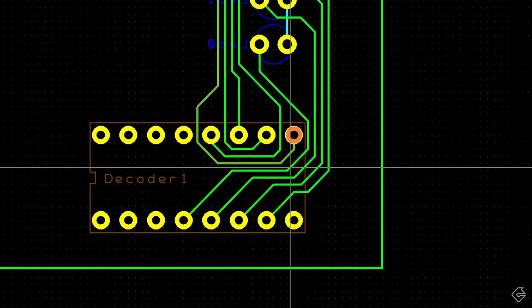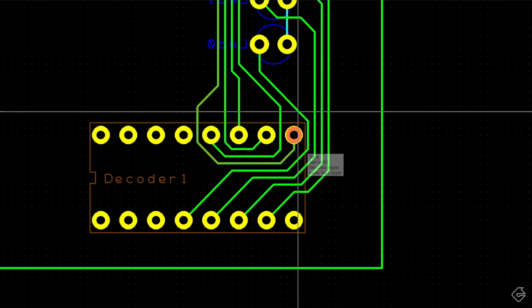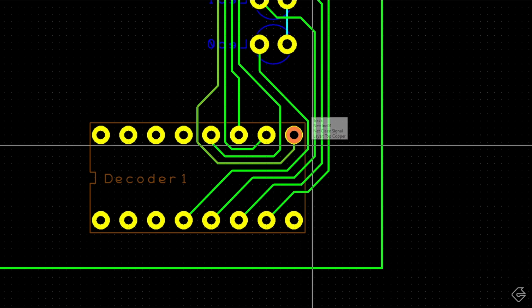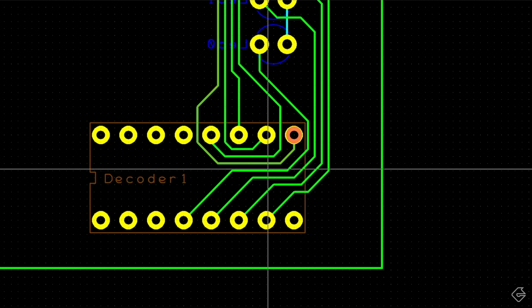I like the aesthetics, actually, of having some of these what we call mitered traces that kind of glide around wherever you need to go, and make sure that you have enough space between the traces. Your PCB design software has rules built in so that you can run a design rule check to make sure that the spaces are adequate and all that. So depending on the way your design software works, there are all sorts of helpers to figure out how this works.